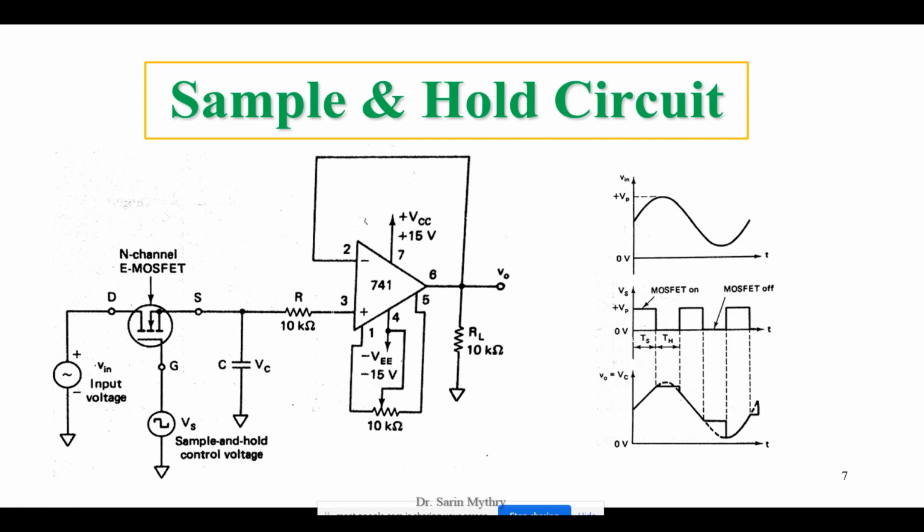So this is called the hold period, since the data stored in the capacitor is held at the output. So there are two kinds of operation in the sample and hold circuit. One is the sample period and the other one is the hold period.